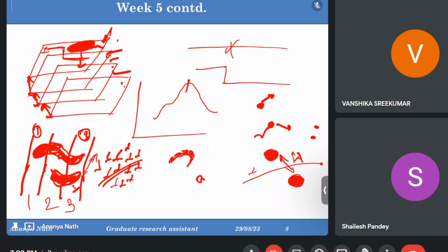For screw dislocations, they move along the Burgers vector, and the movement of the dislocation and the direction of the Burgers vector are parallel to each other. So this is why cross slip in case of screw dislocation is easier. They very easily can cross slip from one plane to another plane because all the planes are parallel and their Burgers vector is also parallel to their movement.